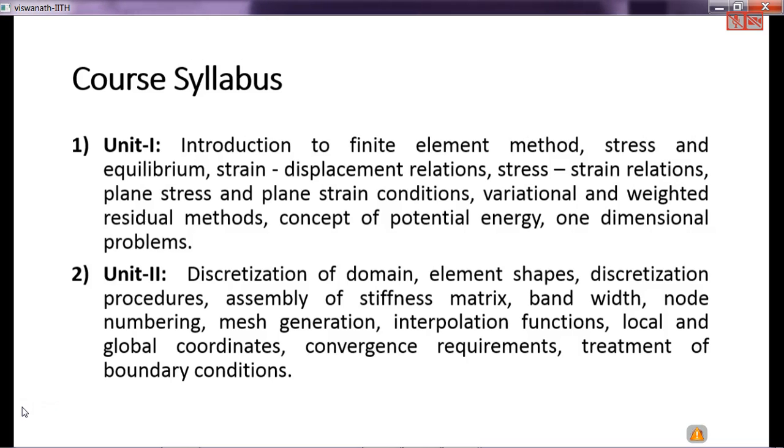So when you're discretizing your complex geometry into subdomains or domains, what is the natural part of discretizing it? If I give more refinement, then I have to wait forever to get the solution, right? Or if I do it very crudely with one element, I may not get the solution I'm promising. So anyway, at this point, I need to stop and explain why I'm telling you this.